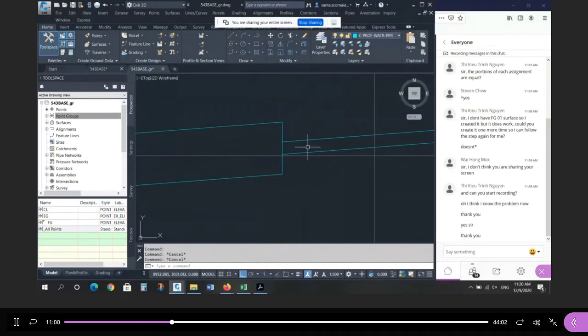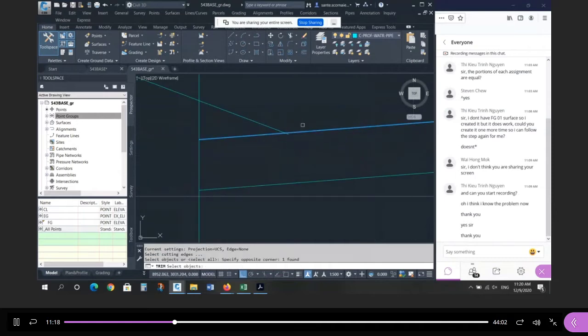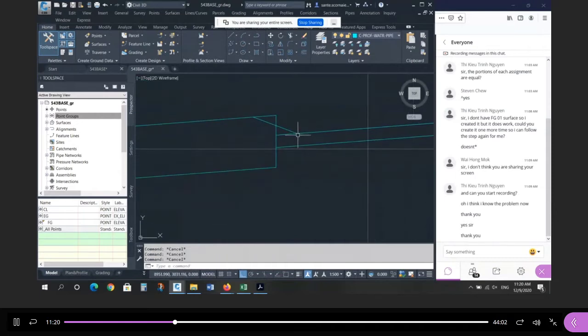Now, if you want to draw it like in the plan view and make it look a little more realistic, what you can do is just draw a line kind of from here to here, and the midpoint of that will be on the mark. And here, say, and extend to here, trim to here. And then I'm going to mirror that.